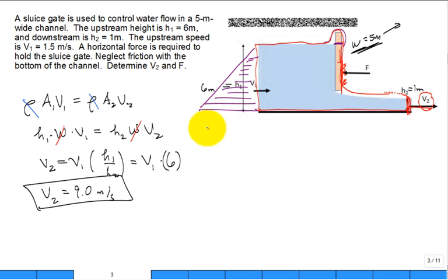So we'll do linear momentum for the control volume. Let's do this. We have some of the forces. What are the forces acting? Oh, I'm going to have a pressure here. I'm going to say this is P1 average pressure, because I know it's a distributed load, but I'm going to replace it and get the average pressure there, times the area. What is the area? Is that the same area that I had over here? Sure, it's the same area, isn't it? That will push it to the right, so we're going to do linear momentum in the x direction. That's in the positive x direction.